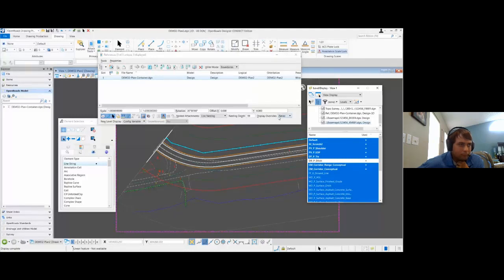Okay, so display overrides, we know if that's set to never, my nested references' level display will always be the same as my nested references in my design model. I think that's pretty easy to understand. And then we also can very easily have one drawing model be different from the others by just going into that specific one and turning the display overrides to all out or always. So that easily allows us to have, maybe we have one sheet that needs a different level display. That easily allows us to do it. But it's only with nested references.